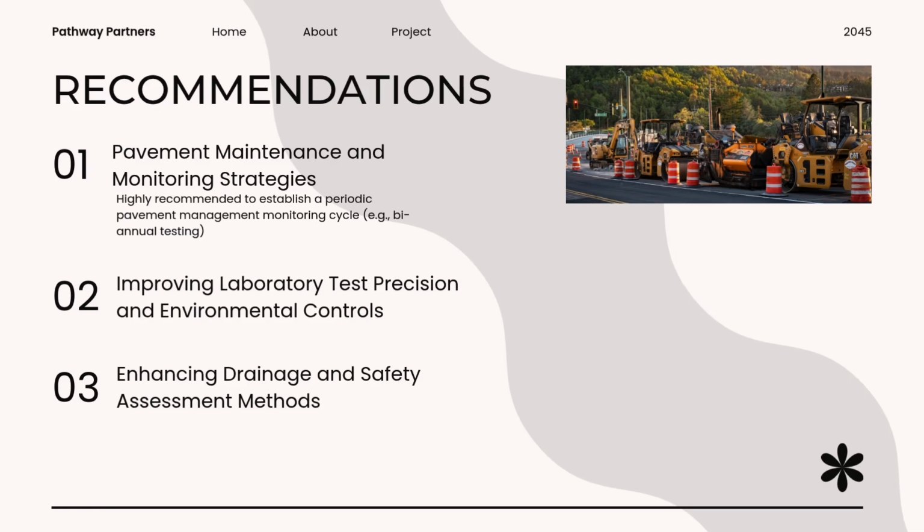The second one is improving laboratory test precision and environmental controls. To improve, strict environmental control must be enforced, such as a windbreak ring should be utilized during the sand patch test to prevent fine sand grains from drifting and skewing the macrotexture calculation.